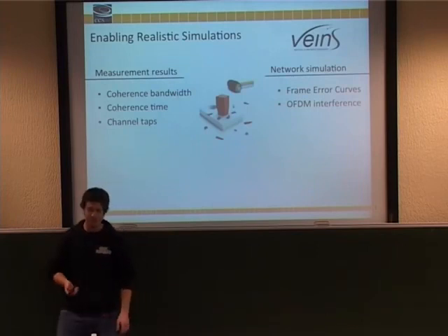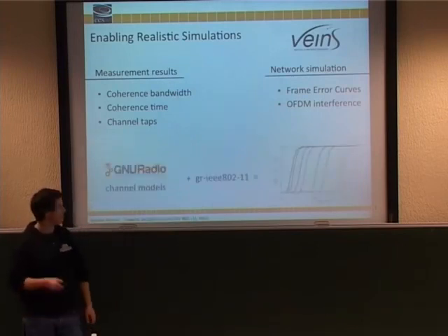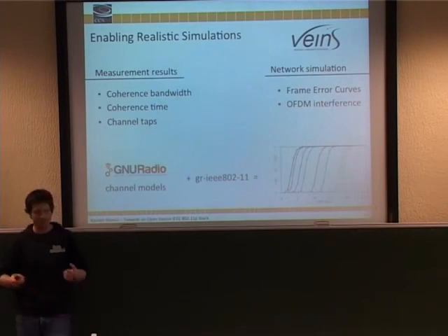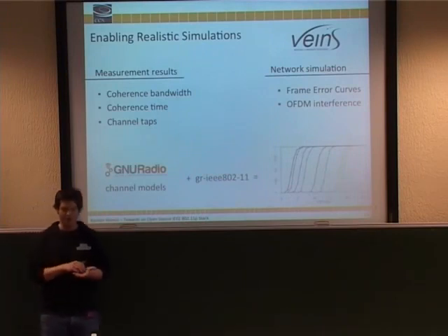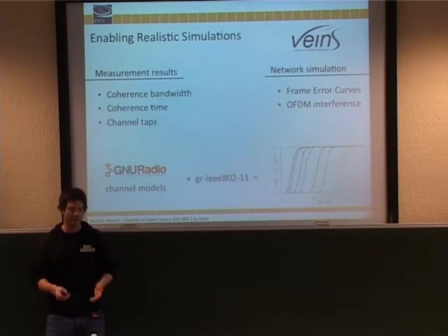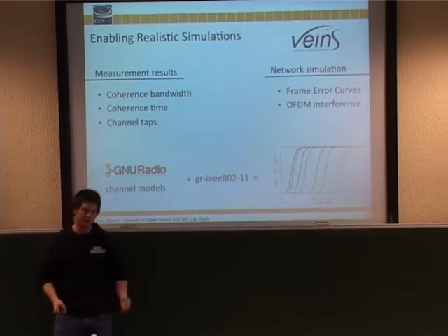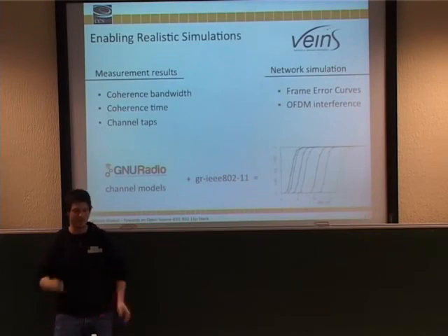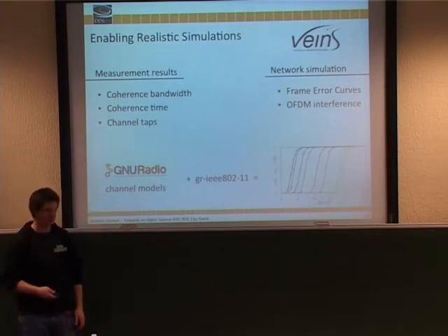And I think maybe with GNU Radio and software-defined radio, you can do that. GNU Radio also incorporates some channel models. You could parameterize these channel models with some data that you already know, that you learned from the guys who were driving around with a channel sounder. You maybe can plug this data in and then do some simulations in GNU Radio and come up with some more realistic error curves that you can then use in your simulator. So maybe these are some applications that are more on the higher layers.